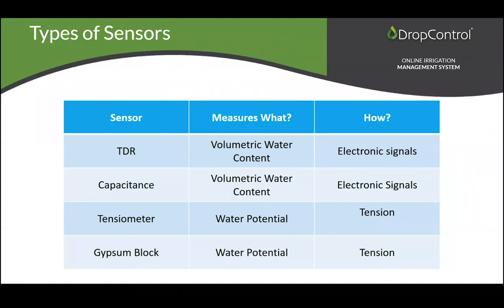There are different types of sensors, and there's usually confusion around which sensors to use. Mainly we have 2 families of sensors: the ones that measure volumetric water content, usually the capacitance probes known in the market, and then water potential, or tensiometers. One is monitoring the amount of water in the soil, the other is monitoring vacuum pressure in the soil. So it's 2 different technologies, 2 different methods to get to the same result, but they are used differently.